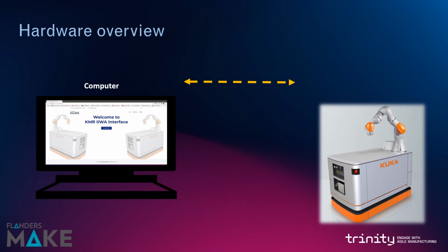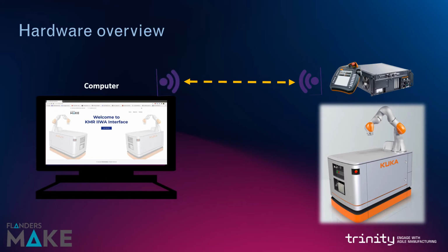You have a computer on the left, which is the external control computer. This computer is responsible for external control and communication via UDP and TCP/IP with the robot, as certain ports are enabled on the robot controller. The following port numbers, client or server socket, can be used in a robot application. That is, the ports are 30,000 to 30,010.